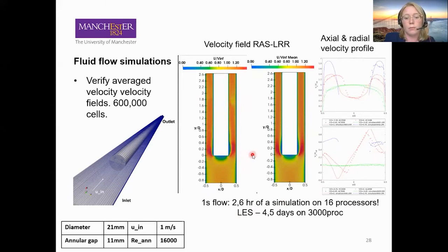Very amazing. For the same configuration, LES would take 4.5 days on 3,000 processors. But actually that poses a question, what if I started from LES? How many processors, how should I decompose the solid side when using LES with solids4foam? That's my question to the community.